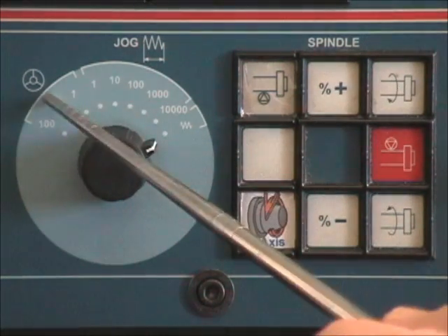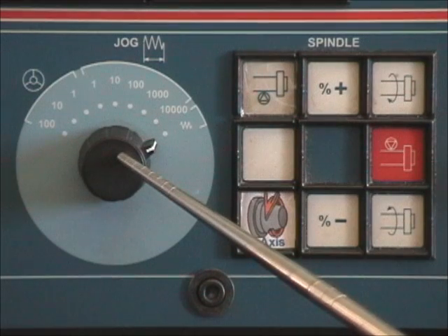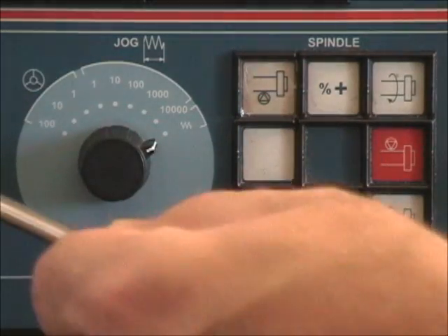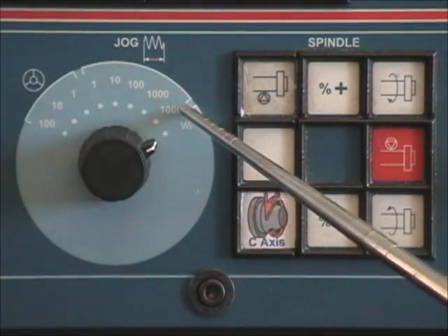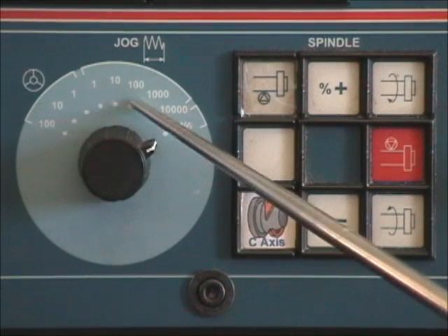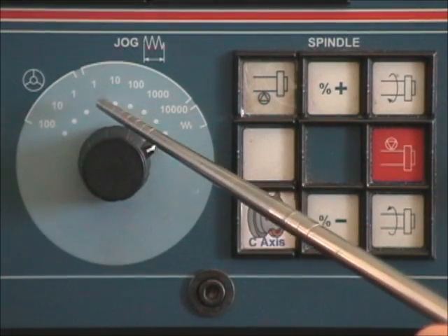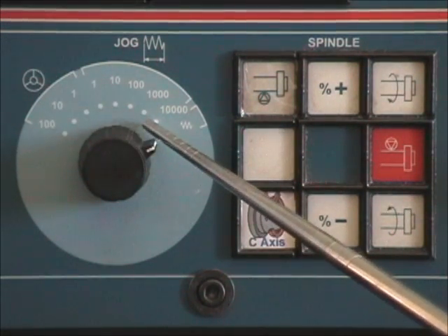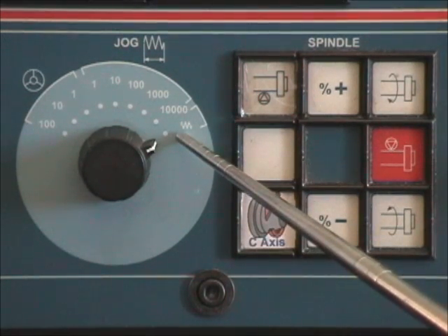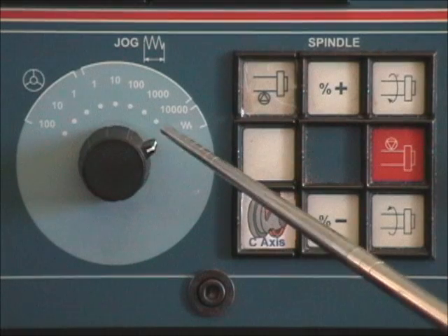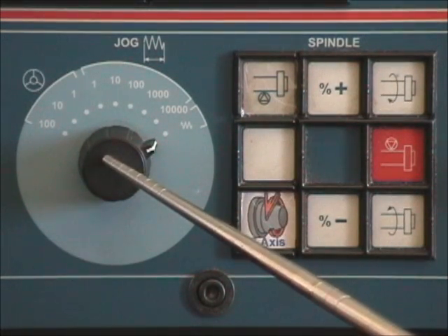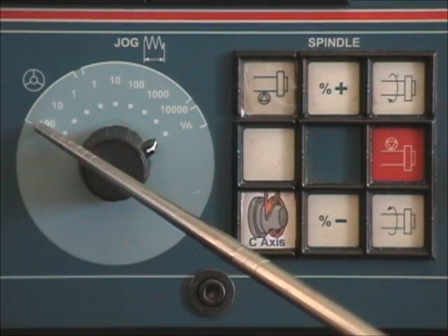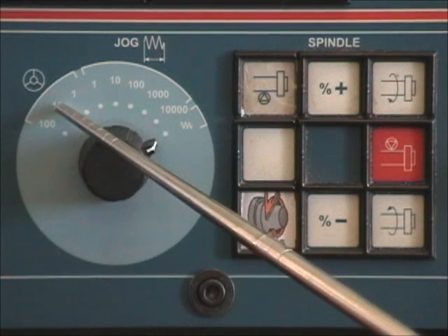There are 3 zones on the mode selection knob. Hand wheel mode and the amount of increment for each axis selected. Incremental jog mode in 5 amounts. Each time a key for the axis is pressed, the control moves incrementally that amount. And finally, the jog feed rate override key. The control is normally left in this configuration, as the GTL 4000 uses a premium hand wheel that has the hand wheel selection mode available.